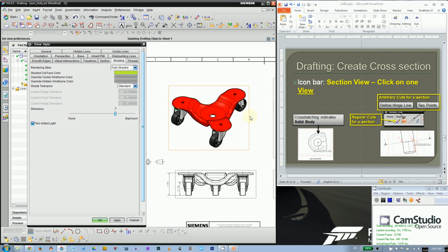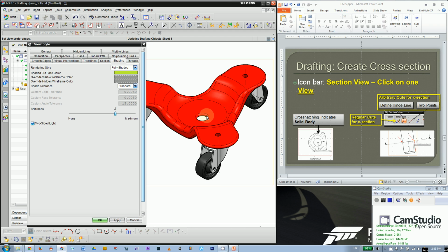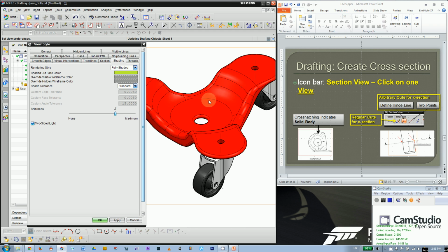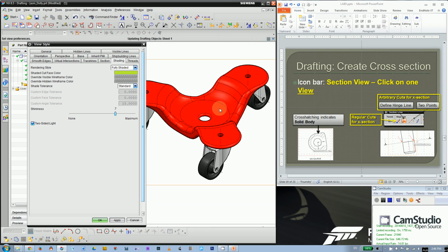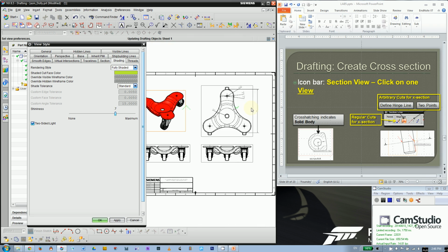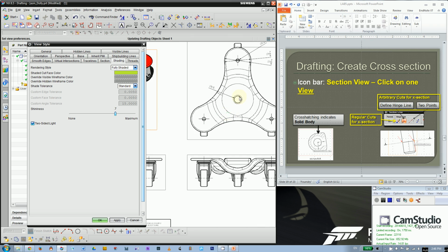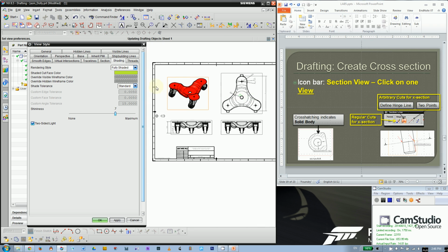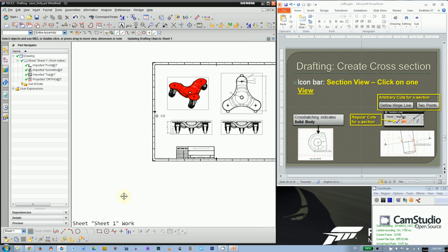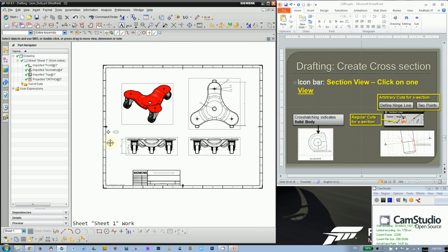However, on this isometric view, you can have some shading indicating the round shape. If you have some geometry without iso lines, sometimes you need a shaded view. Like from here, you don't know if it's concave or if it's coming out. So that's how you change the shading or rendering option of a view.